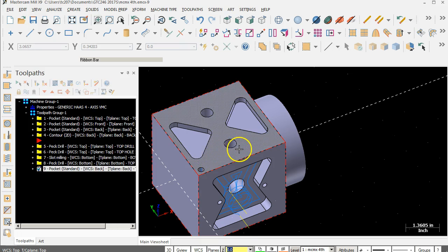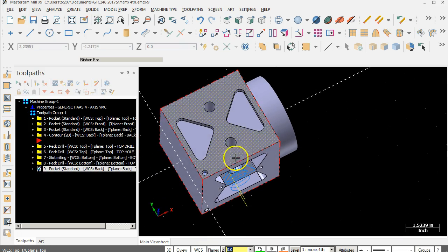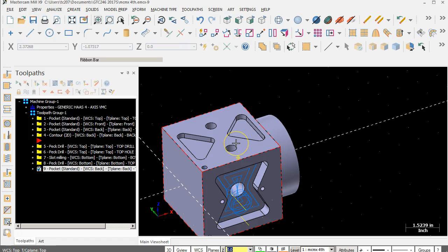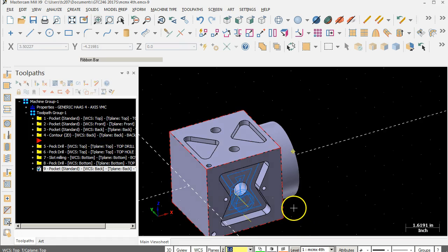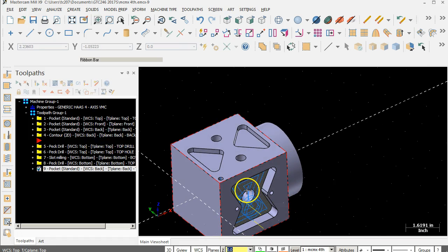Peck went to the 1/2-inch drill, or yeah, peck 1/2-inch. That should have been the only 1/2-inch tool. Said that this is 3/4, so I'll probably take the 1/2-inch tool and go through and open it up so it's not as much load.